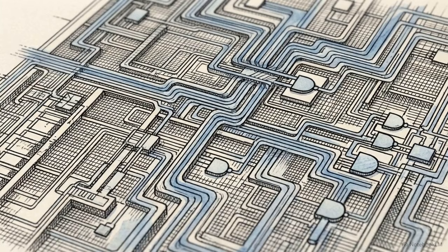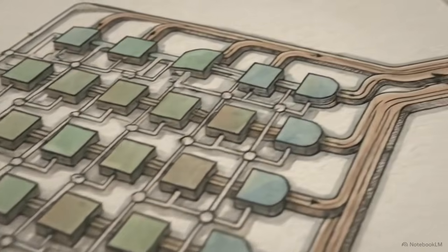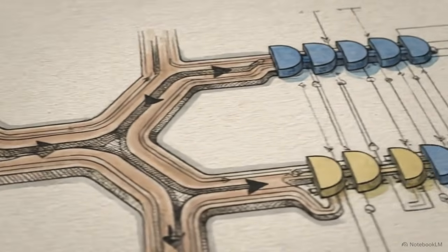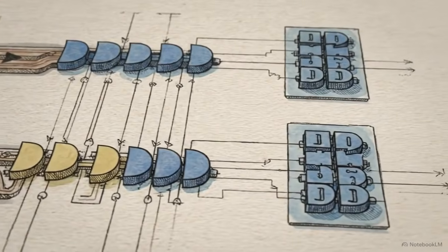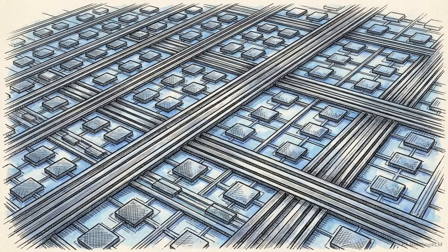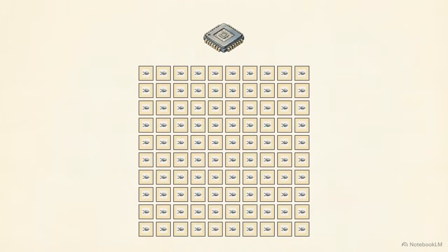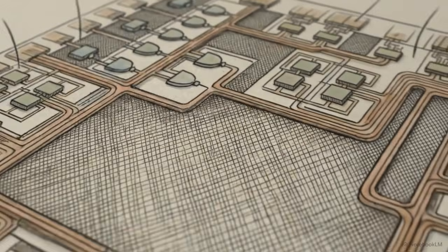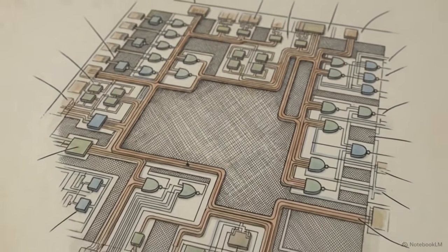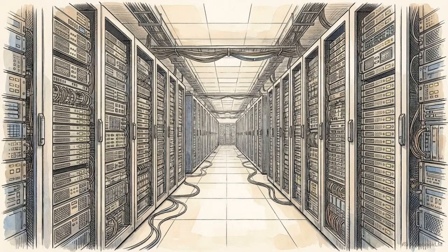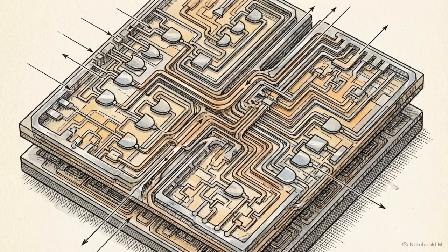Today, hardware designers overcome the physical limits of 6T SRAM by bifurcating its evolution into 2 distinct branches. The access path isolates state nodes with 8T and multi-port topologies to guarantee stable concurrent read bandwidth. The search path embeds XOR logic directly into the 10T cell to execute massive parallel queries. Both paths demand a steep price in total silicon area and transistor count, strictly limiting memory array density. Memory arrays now serve as the frontline computational engines of the digital world. By reconfiguring the topographical arrangement of transistors, engineers have integrated logic into the storage silicon itself.